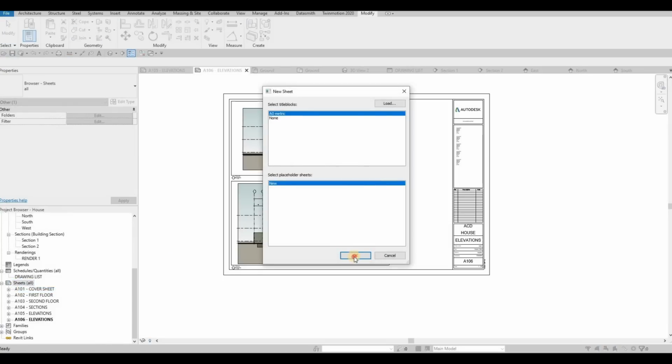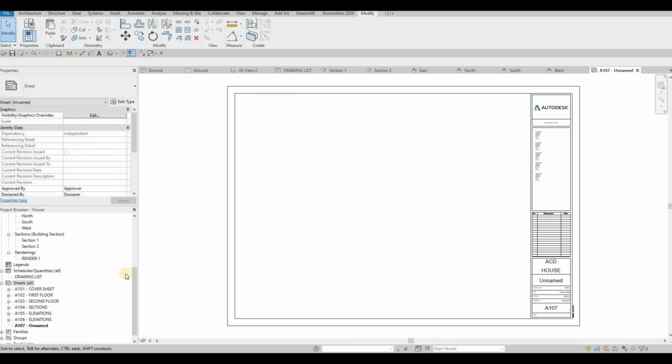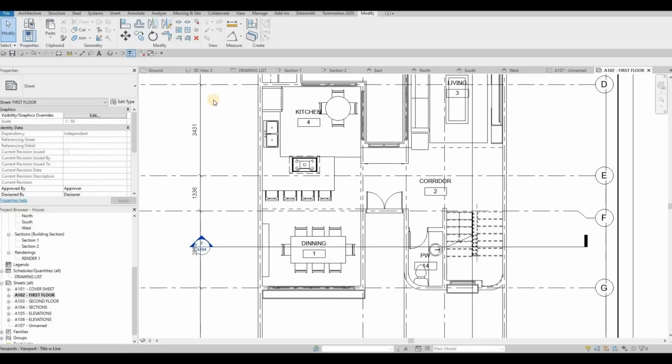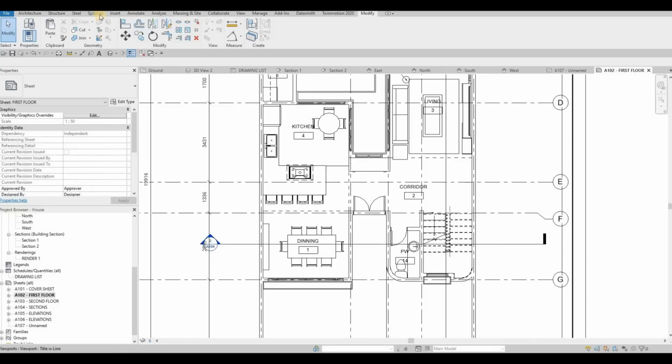So new sheet, axonometric. We're just gonna do probably 2 callouts. So I just want to show you how to create callouts. You can do the callouts for even wall details, and now we're just gonna do a regular callout for plan details. So now go to first floor.